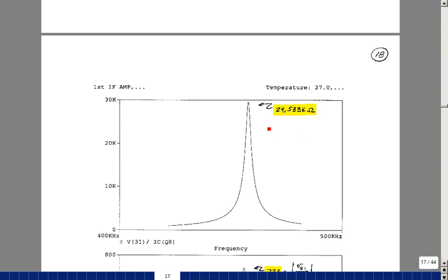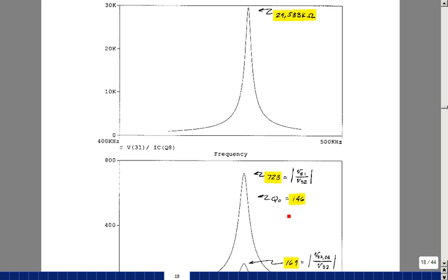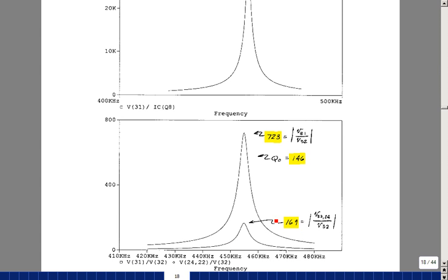This is virtually identical to the value of the resistive load multiplied by the inductor ratio. The voltage gain, about 723, so pretty close to the value predicted of 689. And then the gain at the output of the transformer differentially to node 32 is 169 in magnitude.